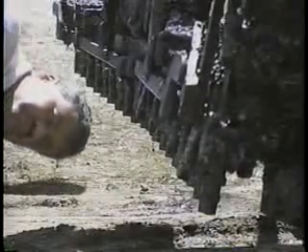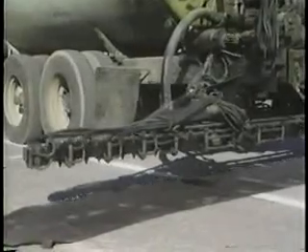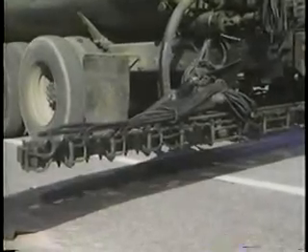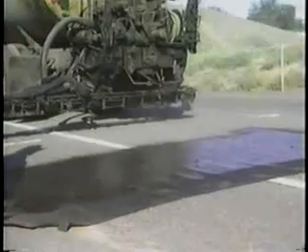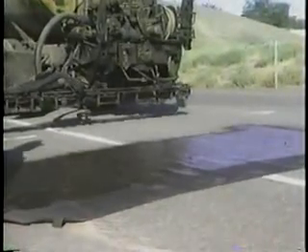To get uniform coverage, first check the spray bar nozzles. They must be unclogged and uniformly angled, usually 15 to 30 degrees in relation to the spray bar. If the nozzles aren't angled properly, the spray fans will hit each other and produce an uneven coverage. It's a good idea to check the spray both before the actual application and soon after startup, so that any problems can be corrected before the operation moves too far.